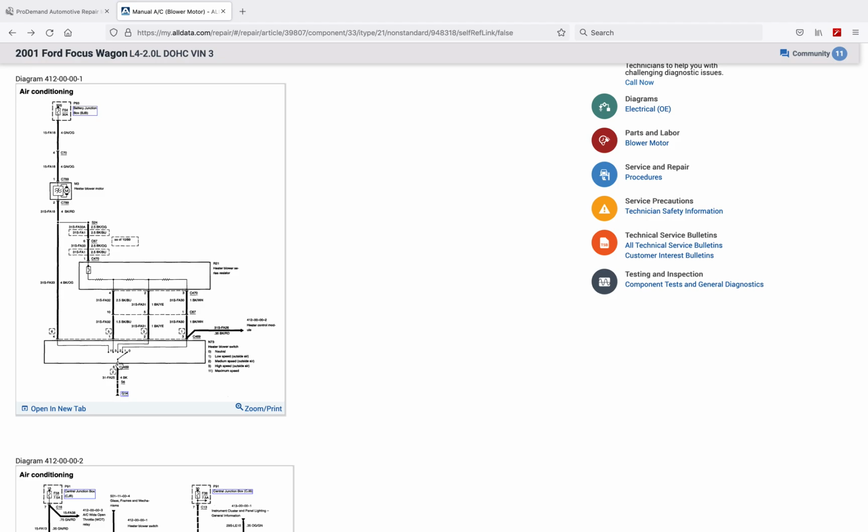So if I go to high speed, which they're calling again position 11 here, maximum speed, I go from my power supply to the engineered load straight to ground. How many resistors do we have in total? Just one. So I've cut the resistive value down again significantly. That's going to force this fan speed to climb and give us our maximum output.